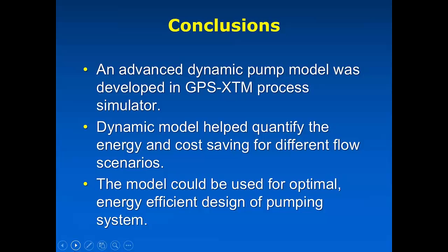Okay, so I realize I've come right down to my last few minutes here. Just to quickly wind things up, GPSX has these models that are built into all of the objects for you. We have that newer energy pumping model, it's been there for a couple of releases now, where you can actually go beyond just having a constant efficiency and actually enter in your own pump curve. And that particular model also allows you to define fairly sophisticated ways of operating those pumps, and you can do a lot of really interesting things with those.